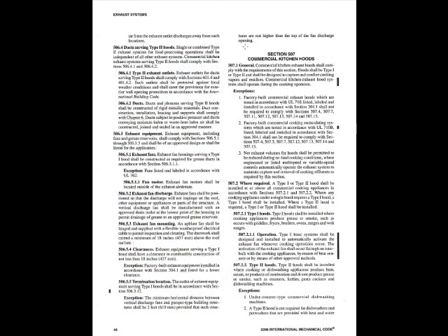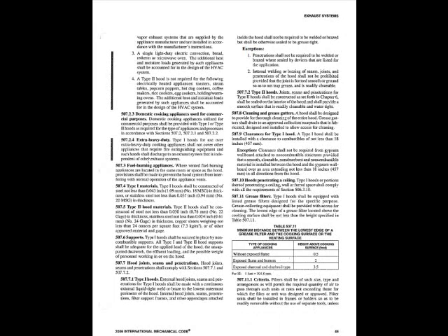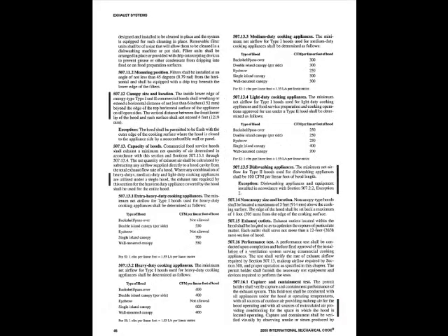Section 507 talks about commercial kitchen hoods. That's the inside of the exhaust system. It feeds the exhaust. And it will come down here talking about flames. Height above cooking surface. If without an exposed flame, half a foot. With exposed flames and burners, 2 feet. So it's very important you understand the different exhaust systems and the requirements.